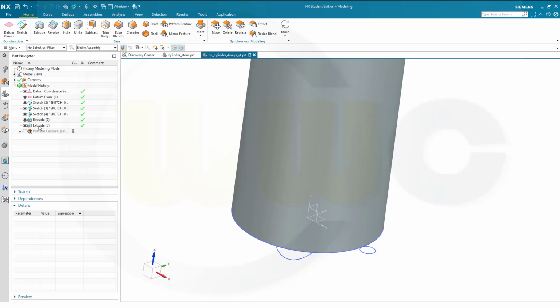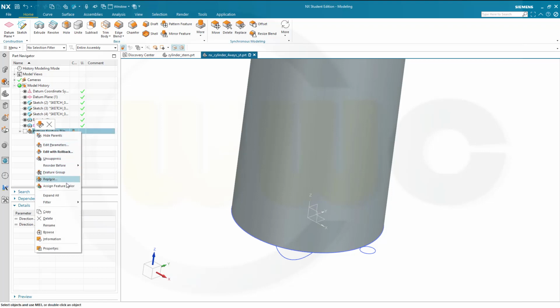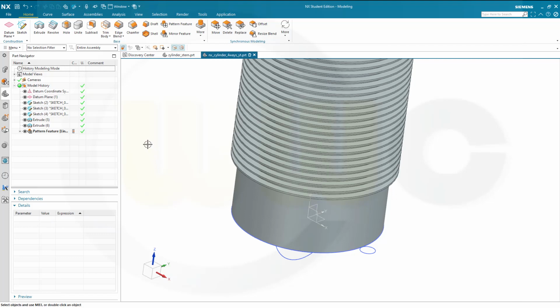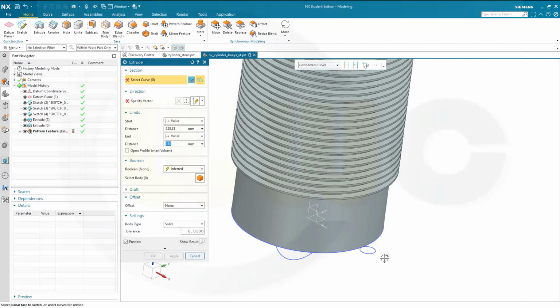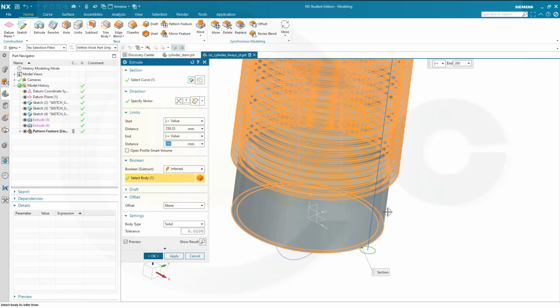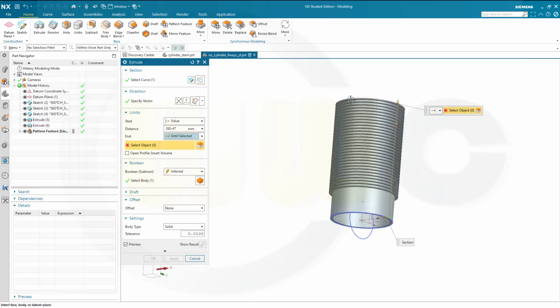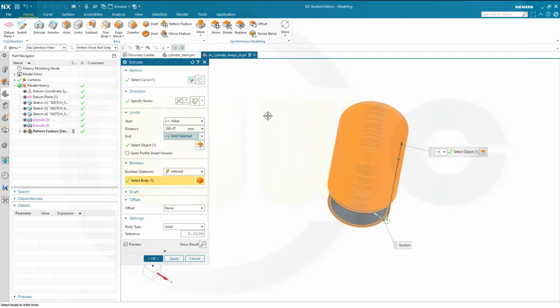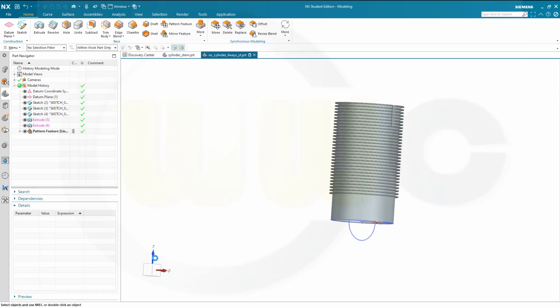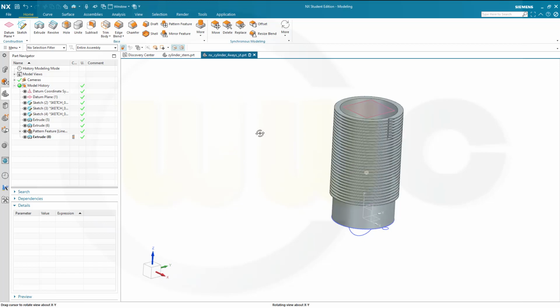So I've suppressed this one and I want to make a new, so I could unsuppress and now go for that extrude here with that sketch, and see, it already works. So that's the start value. It's 260 minus 47, 260 minus 47, and this should go until selected, until that plane here, and confirm. Let's take a look if it worked.